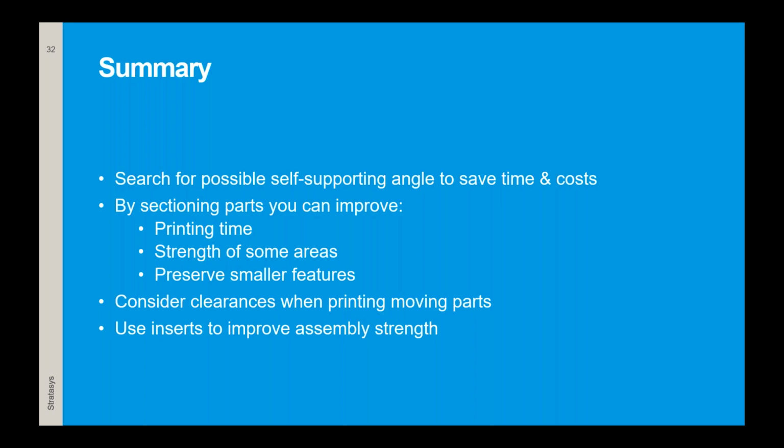When you are printing moving parts or having an assembly, consider using clearances for those parts so they do not fuse into each other and are able to move later on. And by using different kinds of inserts, you can improve assembly strength quite a lot.